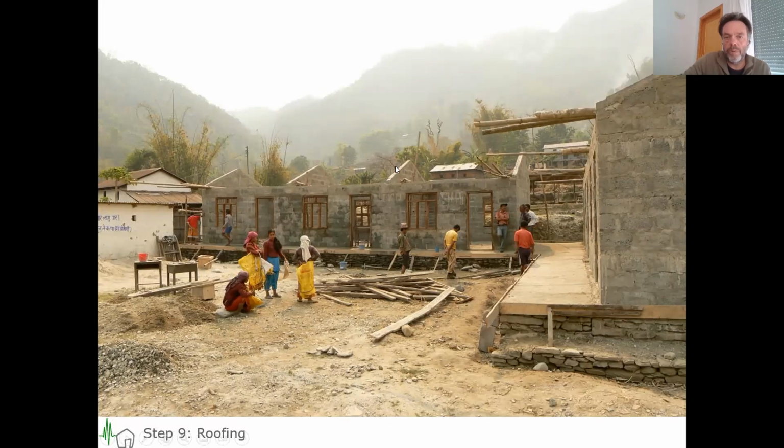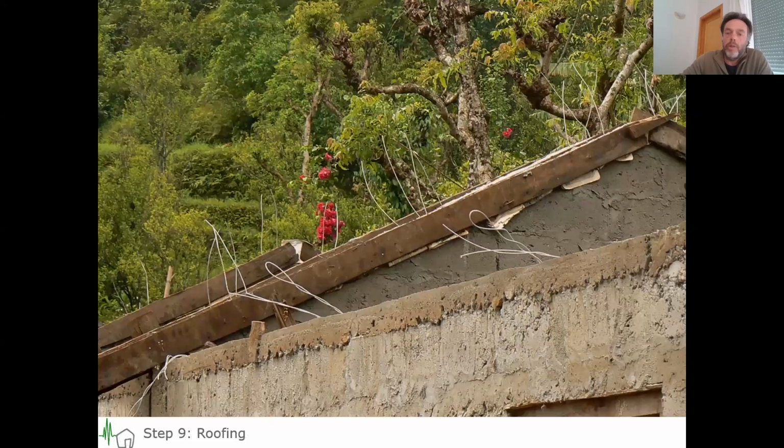The first ones we still built gables, which is also something that we changed later on. But what you see here is this galvanized steel wire sticking out of the top beam. We also tried to cast these gable beams, which are very difficult to cast anyway. And you get very weak connections where these beams come together.